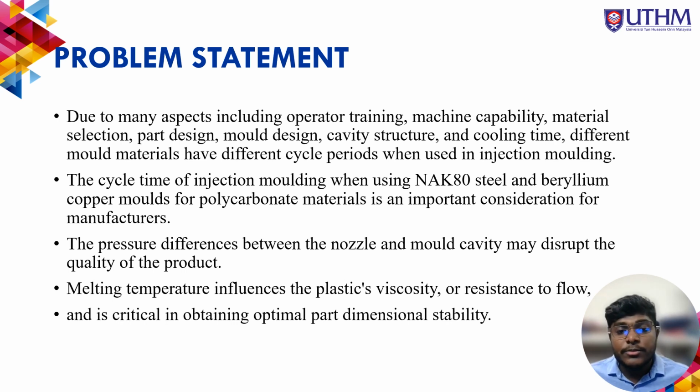The pressure difference between the nozzle and mold cavity may disrupt the quality of the product. Melting temperature influences the plastic viscosity, or resistance to flow, and is critical in obtaining optimal part dimensional stability.